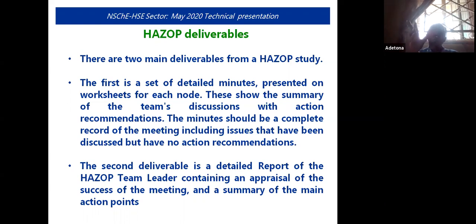However, there could be instances where the HAZOP team members, who have the project management team members in place, can feel that a particular safeguard, which is low or medium, is adequate. The HAZOP team leader, based on his experience, can come out with a higher level of protection. And whatever he puts is owned by him. It's not answerable to the management. It comes to protect his integrity and his wide experience.